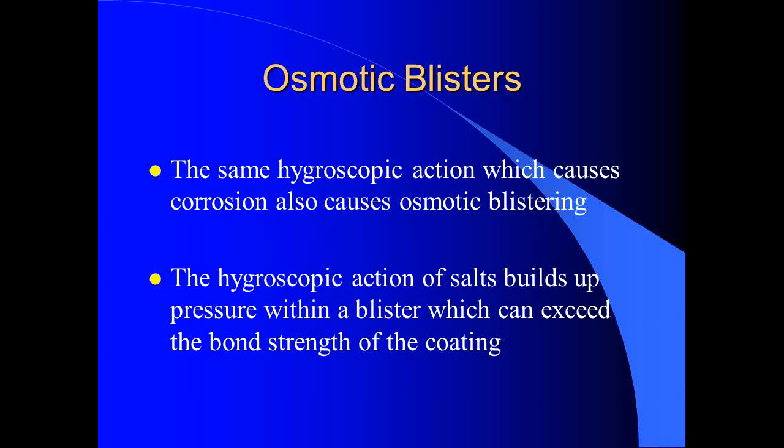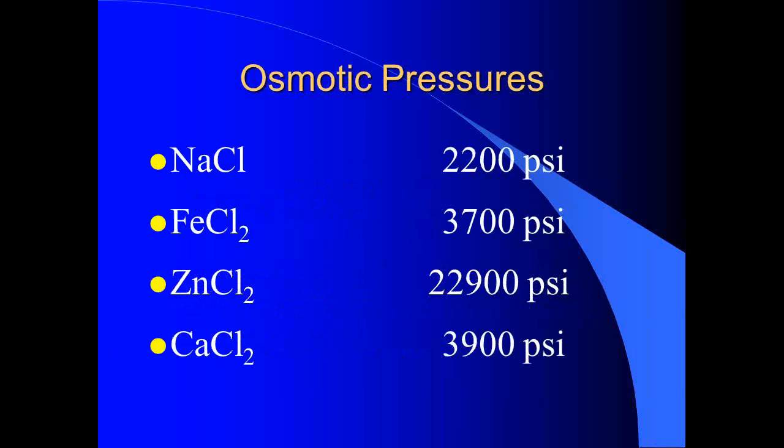What we typically encounter in tank linings, bridges, and everything is in the 600 to 900 psi bond strength range. Now I haven't been able to verify the accuracy of these numbers with this PSI. Still searching for the original research work that came up with the numbers, but as a general rule, they're pretty close.